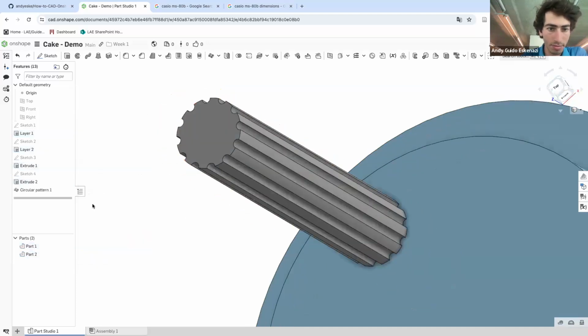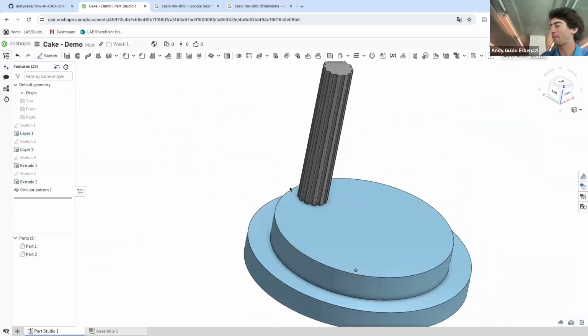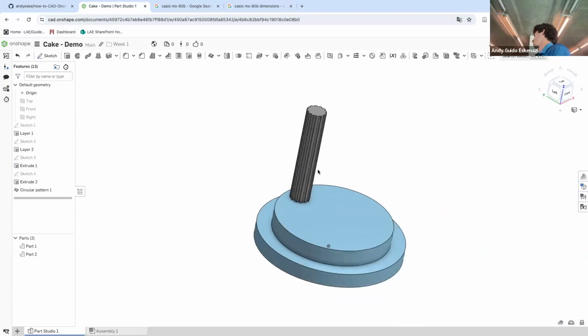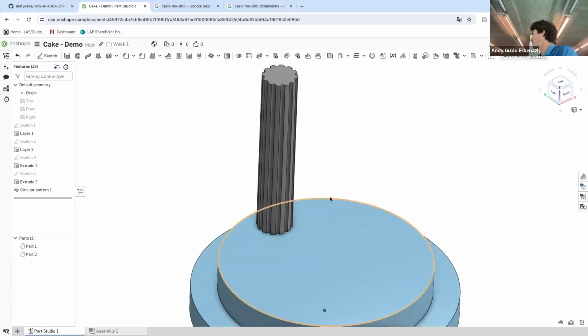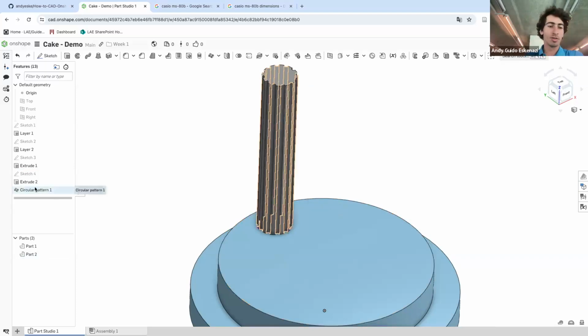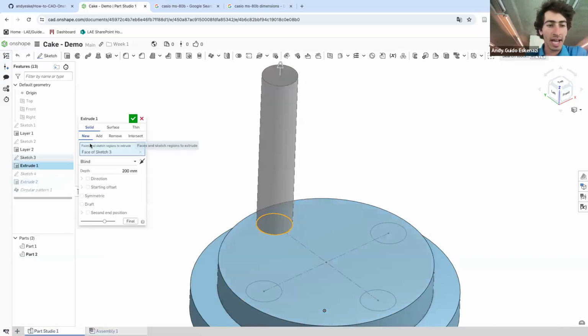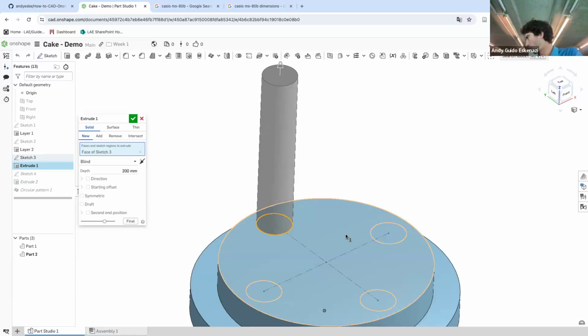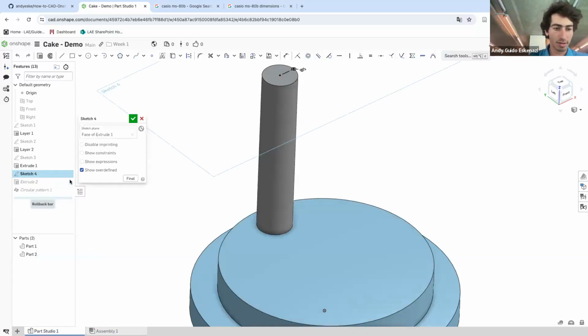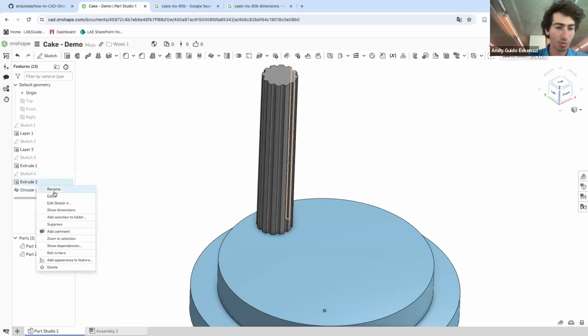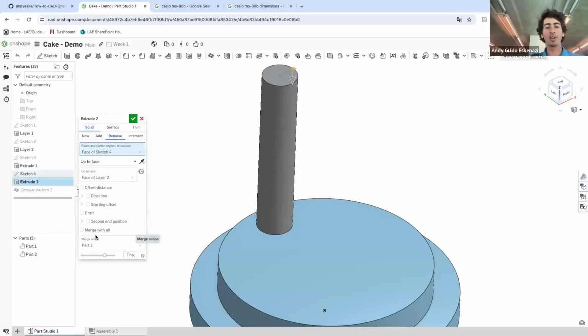There we go. So this is normally a little trick that you would need, but now these are different parts. Normally we like designing things as a singular part, but now it's as if this column was dissociated from this base. The way I did it was that I went here to edit, and instead of saying add, which will make it all the same part, I just said new. It's asking you when you edit what the scope is, so I said I want this to be part 2.